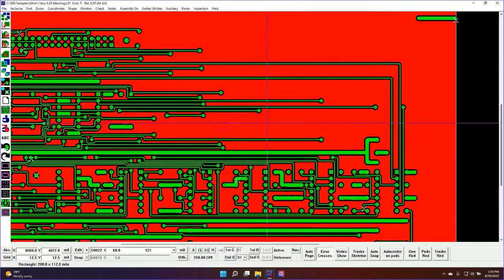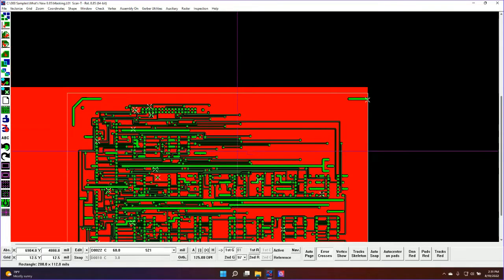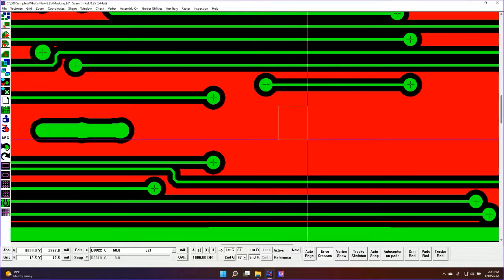And so now you can see how this function works and why it's a really powerful function, because generally speaking, especially in like LTCC type applications, you're not super worried about additional conductor here. That's okay. That's not going to cause problems. And so having the ability to just define a quick mask based on the inspection Gerber and a threshold is going to make things very easy.